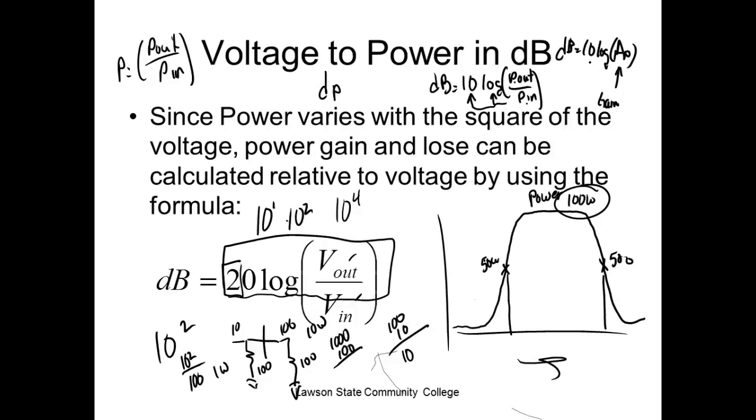You're matching it to 300. So you got a 300 ohm antenna. Well, it don't match to a 50 ohm input. So you put that little impedance matching transformer on there, and that converts it over from what? From 300. So on this side it's matched to 300 on that little impedance matching transformer. The other side is matched to 50. And you couple through a transformer. That's all that is. It's nothing but a transformer.